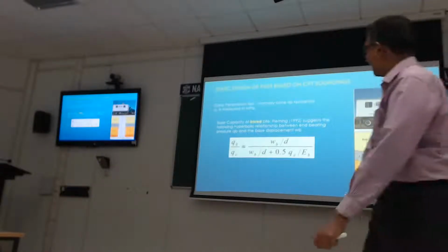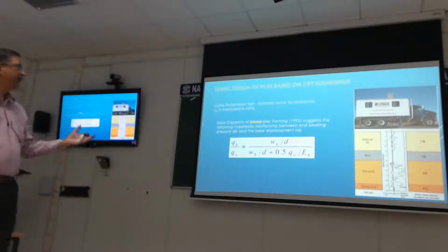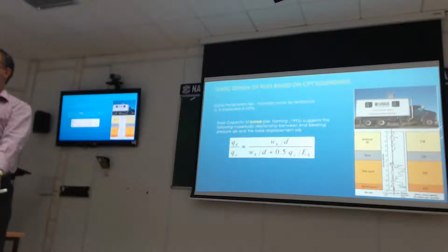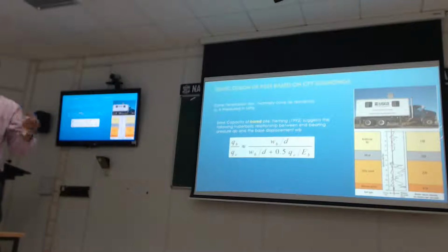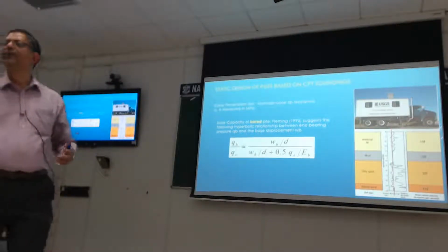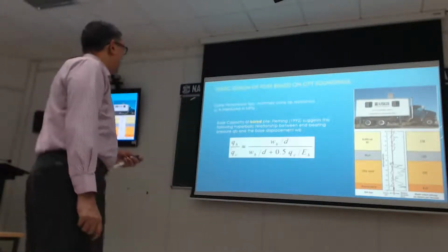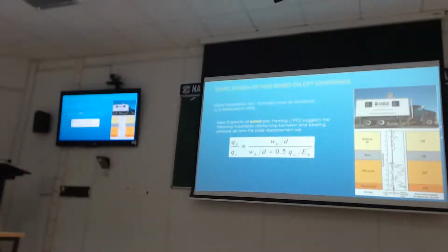Now, once I have this, as I said, in the UK, we tend to design bored piles more often than not because we can make very quickly a hole in the ground, and the hole stays open because our clay is strong and over consolidated, and we can pour concrete before it caves in. So bored piles form about 80 to 90% of the piles in the UK. So it's important for us to estimate the pile capacity for bored piles.